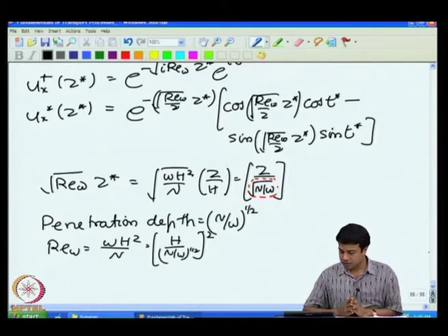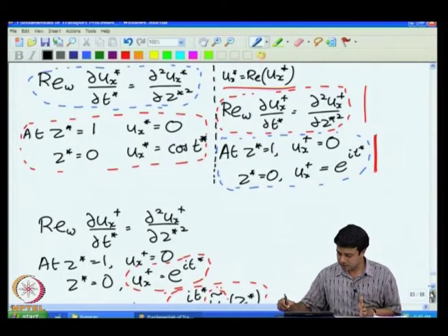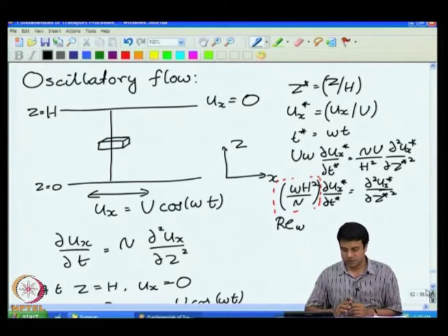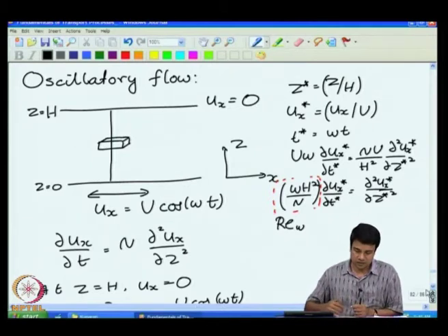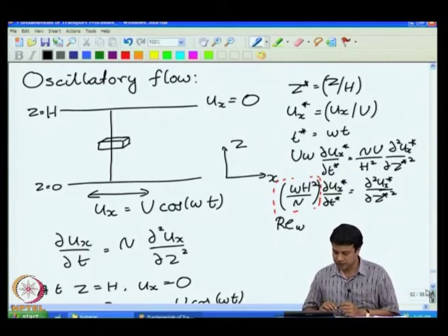Similar problems can also be posed for concentration and for mass and heat transfer. They are a little more difficult to realize in practice. In heat transfer, you would have to heat the bottom plate with a sinusoidal temperature. It can be done if you have a heater with the correct frequencies. Mass transfer is much more difficult to realize. You cannot very easily have a sinusoidal variation. There are oscillatory reactions, but it is not very easy to realize in practice to have a sinusoidal variation in the concentration of the bottom surface. So, this is how we deal with oscillatory flows.